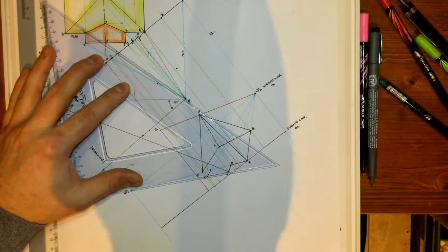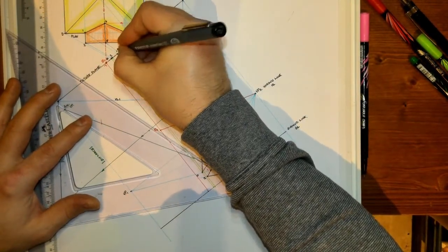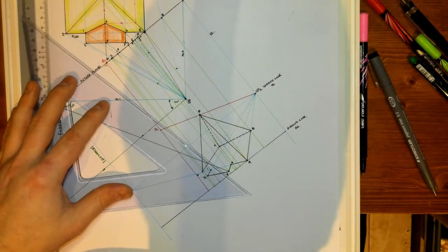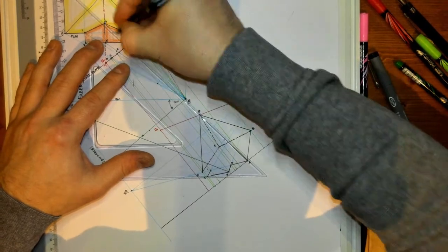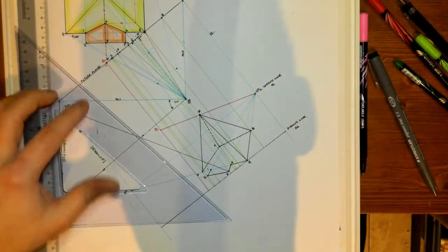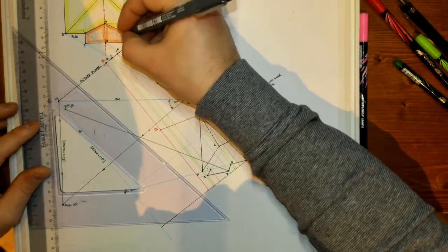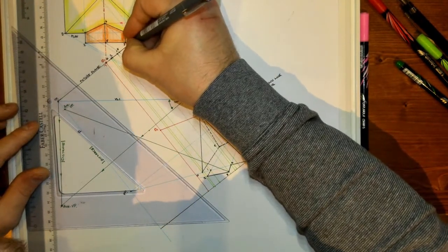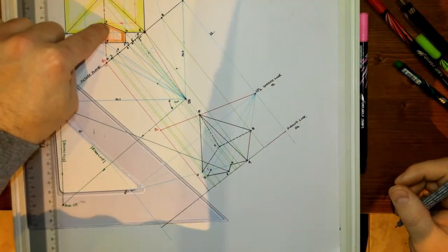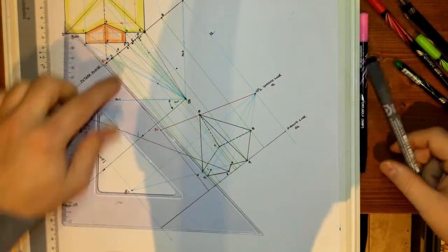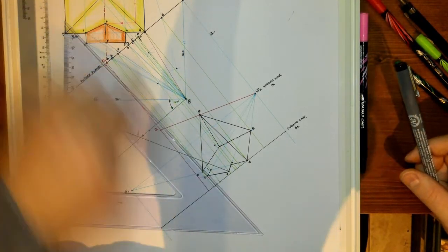Like so. As I bring the first one back, note where it crosses the picture plane. 5. Line up point 6 with S. Okay. And note where point 6 passes through the picture plane. And it virtually lines up with point 3. So that's a coincidence. It lines up with point 3. So we can assume that the line for 3 also is representing point 6.